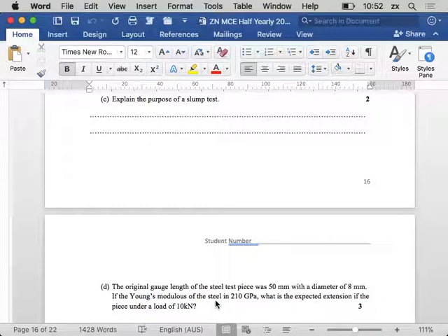Okay. If I said describe the slump test, what would I be looking for? Put concrete in a cone and describe the process, the method of it. Put concrete in a steel cone. You use a rod to make sure it's worked in properly. And then you tip the cone upside down, and you look at how much the concrete falls apart, how much it slumps.